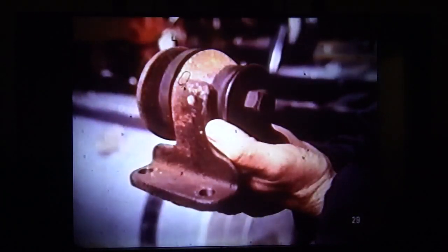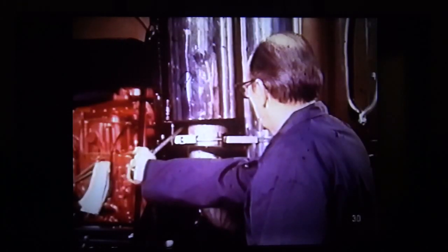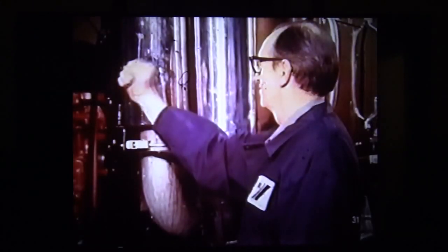If the engine is operating properly, the next step would be to check the engine and transmission mounts. Check to see that they are properly secured, that the rubber insulators are not compressed too tight or damaged, and that there is no metal-to-metal contact. If the mounts are defective, they should be repaired and the vehicle tested before proceeding with the inspection. Next, check the exhaust system components and their mountings to make sure they are intact and positioned correctly. Loose baffles in a muffler could also be the source of a complaint. Make any necessary corrections and test again.